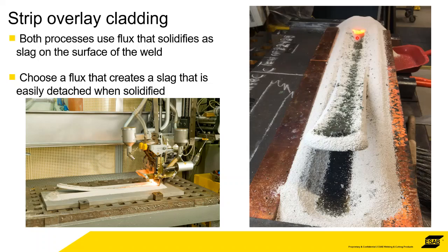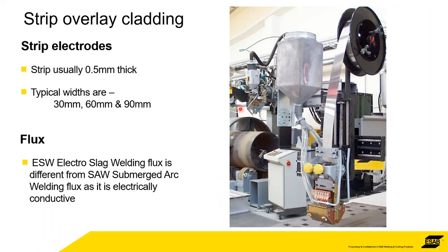If you're having to mechanically remove slag, either grinding, chippers, whatever, hammers, then that obviously adds hours onto the production time. So there are fluxes available. There's a very big range of fluxes to choose from, depending on what you're trying to achieve.